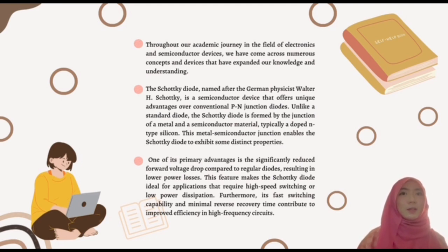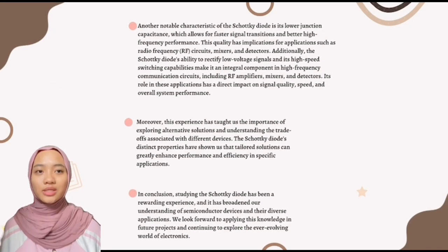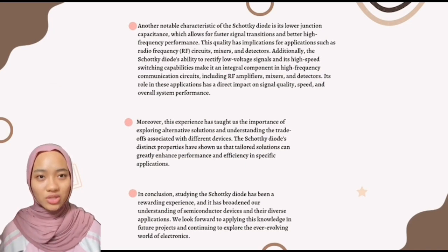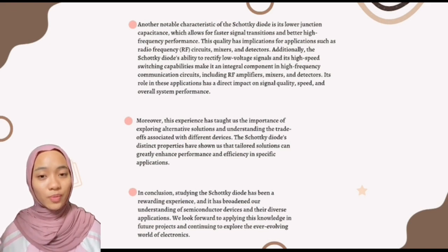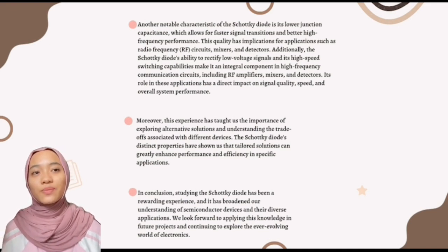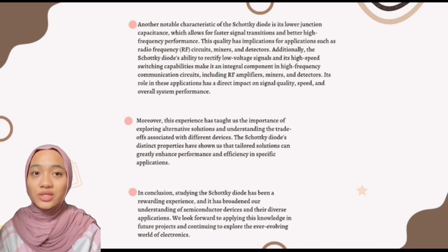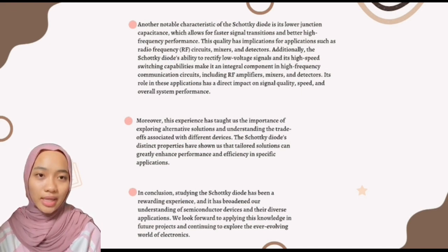Furthermore, its fast switching capability and minimal reverse recovery time contribute to improved efficiency in high-frequency circuits. Another notable characteristic of Schottky diodes is their lower junction capacitance, which allows for faster signal transition and better high-frequency performance. This quality has implications for applications such as radio frequency circuits, mixers, and detectors.